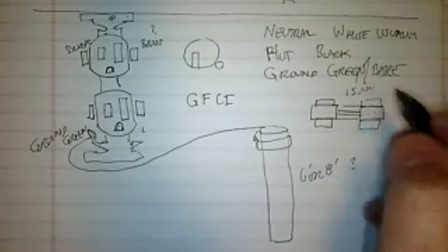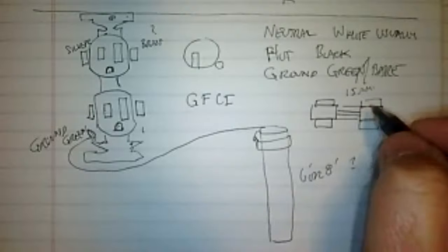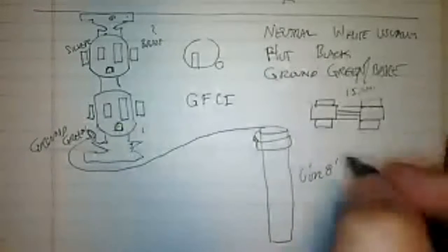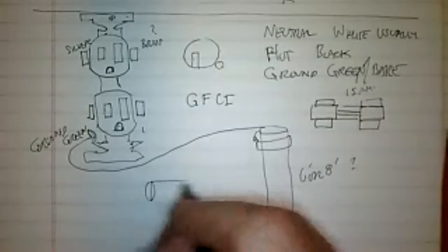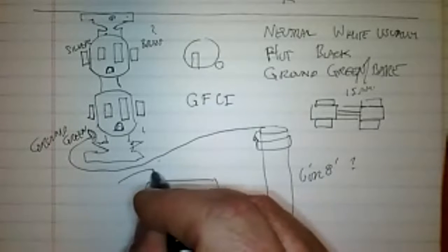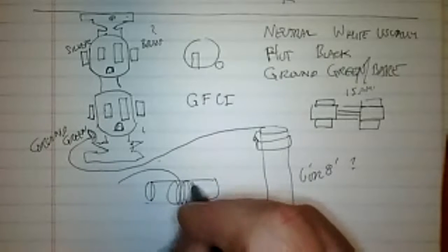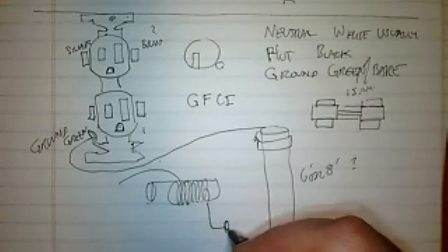So it's not a good idea to replace this with a screwdriver shaft. Okay. People do that. Do not do that. It's not good to put pennies in there, any of that kind of stuff. All these things are meant to protect you. The other way is they use circuit breakers, and that's sort of like the device I was just telling you about. We can make an electromagnet if we take the wire that comes from it and wrap it around it a bunch of times, and then connect it to this.